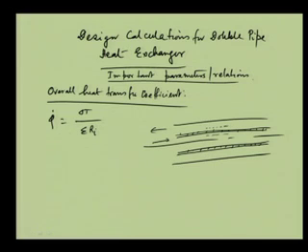And these equations can also be written as Ai, the surface area of the inner tube, times Ui, the heat transfer coefficient based on the inner tube area, times Ti minus To. Ti is the inner tube temperature and To is the annular temperature. The temperature difference is the driving force, and that can also be written as Ao Uo times Ti minus To.